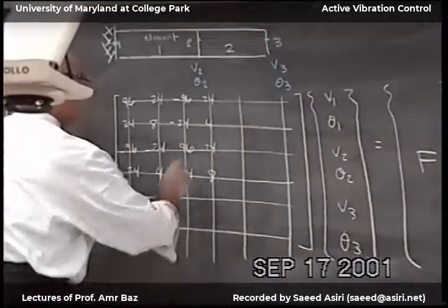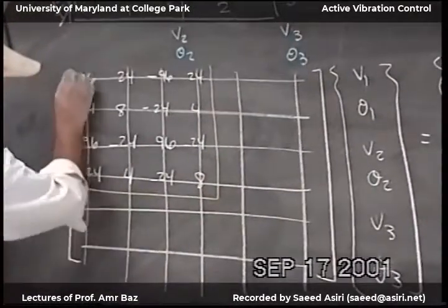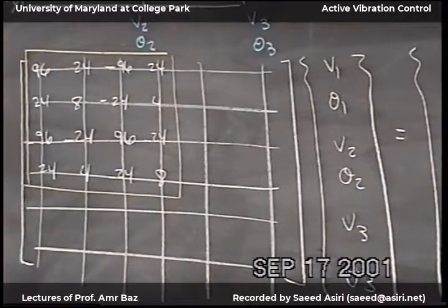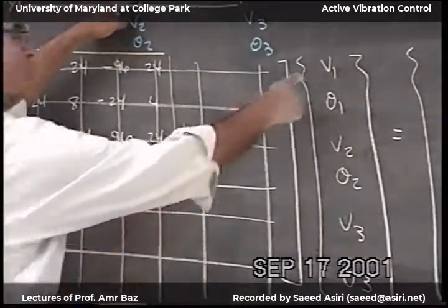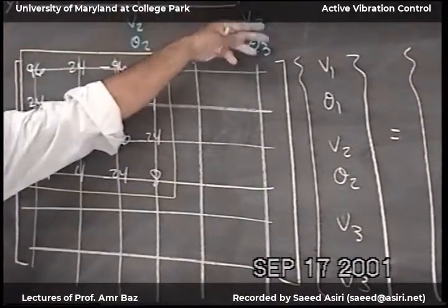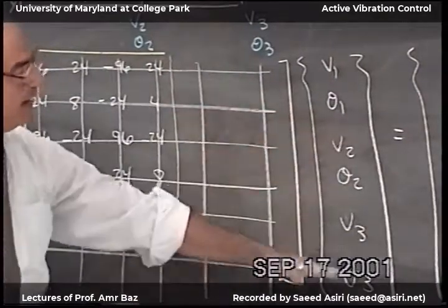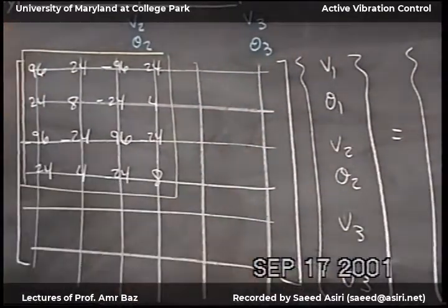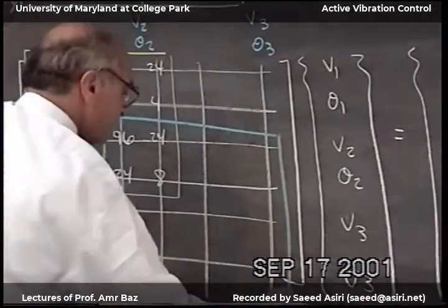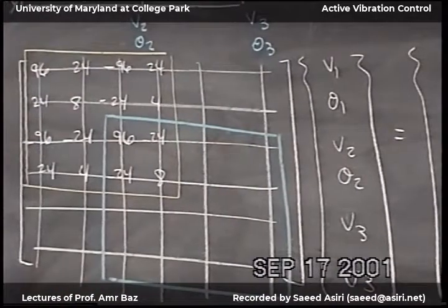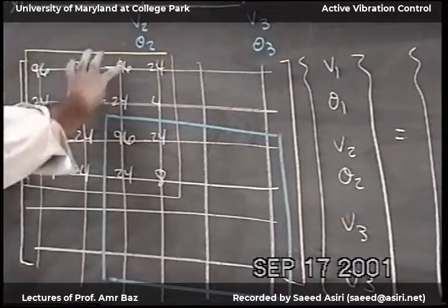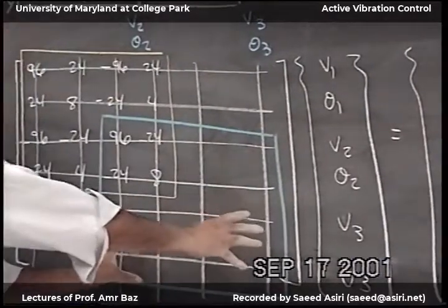So this is the first element stiffness matrix between 1 and 2. So we have 1 and 2. Now the second element is between 2 and 3. So it will extend between 2 and 3. 4 by 4. So this would be here. They are exactly the same. So I'm going to take this yellow block and slide it down until it fits on the blue block.